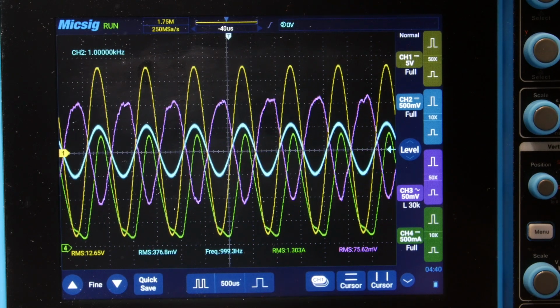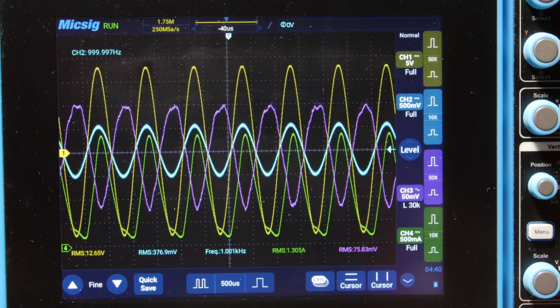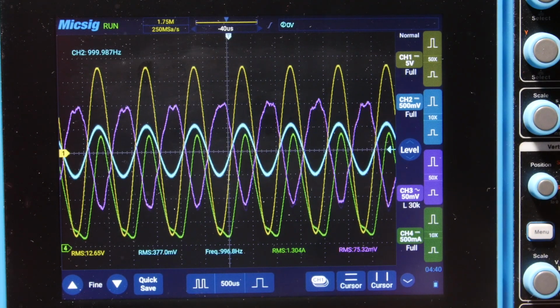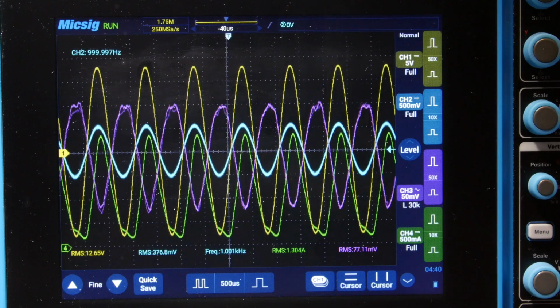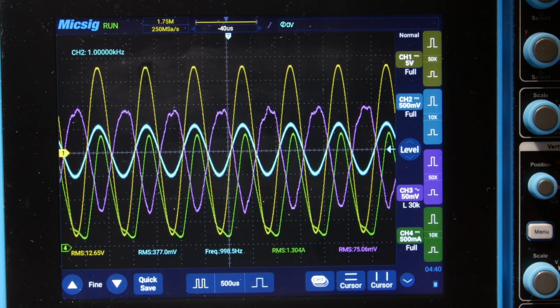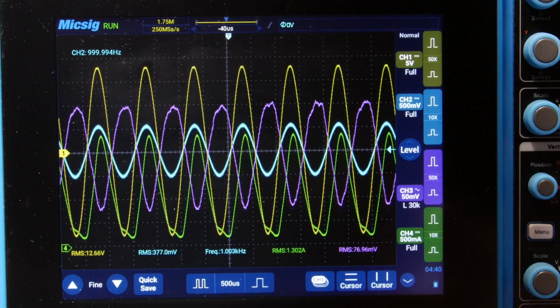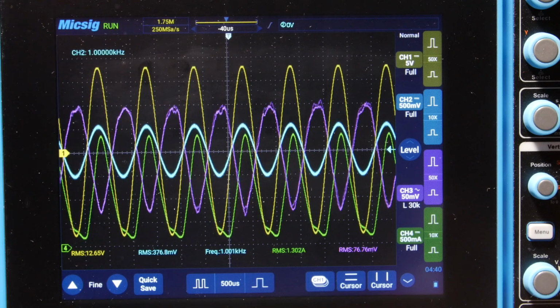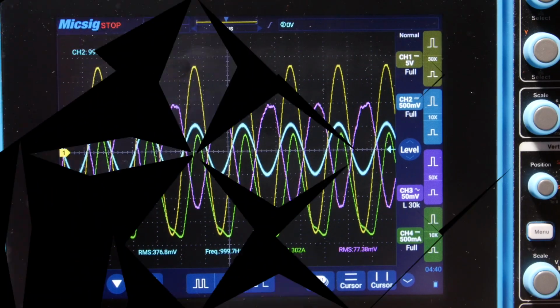But I do start seeing the distortion get affected when I'm dropping down to, okay, I'm at 28. Right about just under 28, I see the THD just climb a little bit. It goes from 0.03 to about 0.035 or 0.037, 0.038, and let me see, 0.04. Let's see how low we can go. Okay, it's right about 27.7. We're hitting about 0.04, so it's gone up just slightly. We don't see any clipping, right? I'll freeze this, turn off the power supply.